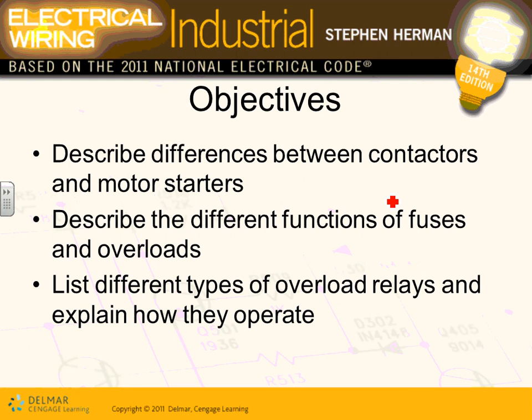Okay, difference between contactor and starter. You're going to hear this terminology, motor starter and contactor, all the time. I hope we talked about these before. A contactor is nothing other than a switch, open and close by energizing a coil. A motor starter, you're looking at a motor starter right here, guys. It has a contactor and an overload. So if you put a contactor that opens and closes, and you add an overload plus the contactor, that will get you the starter for the motors.